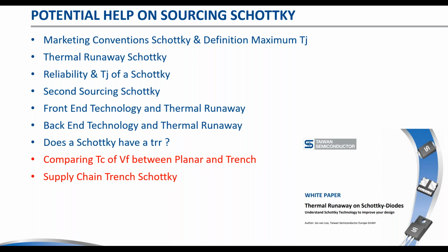So if you start at 100 degrees C, you'll see that the planar is catching up with the trench, or is close or similar at least. So please, in the future, everybody compare the VF of diodes at higher temperature in the curves. That is one way of doing that.